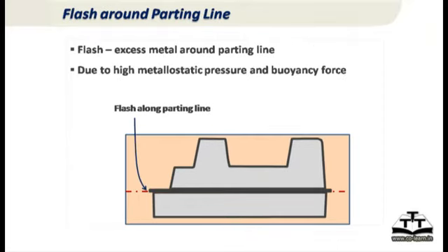So you finally got your mold pattern and the mold cavity, then you actually make the casting, then you realize that you have a real process problem. There is a flash and the two parts are lifting out. Flash comes because the cope is lifting up and the part vertical dimension is now changed, which you never thought about before. I'm adding additional allowances here. In fact, this is not an allowance, it's a natural automatic allowance applied by the process itself.